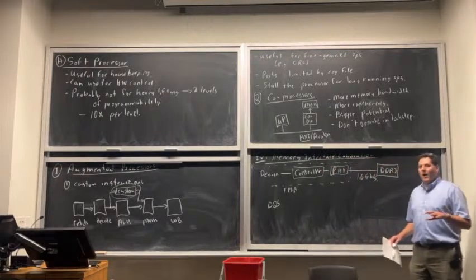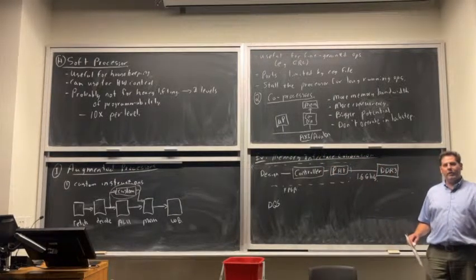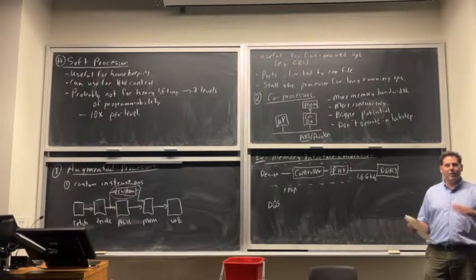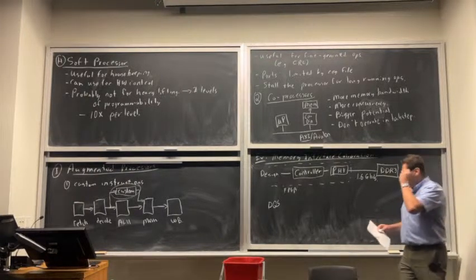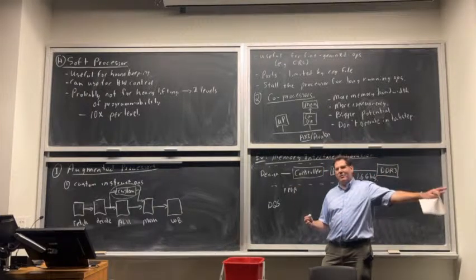As you go to higher speeds, you can't do that anymore, because getting the clock to all the chips aligned with the data proves impossible. You can't have a central clock that all the chips listen to and use to sample the data if they want to send data at high rates. So that's the really simple one.